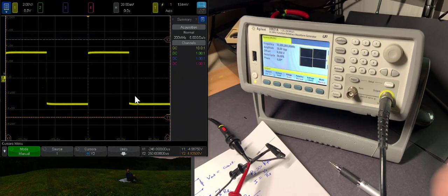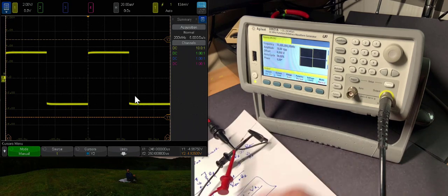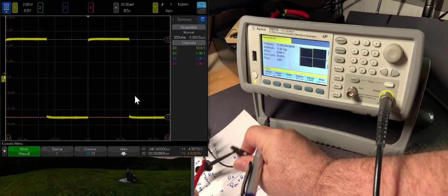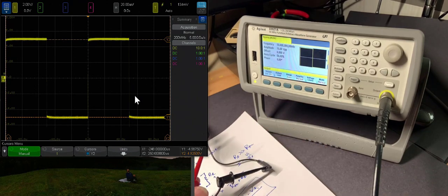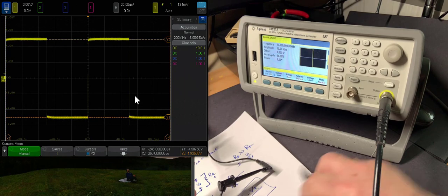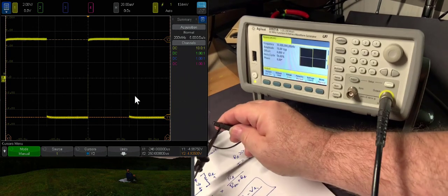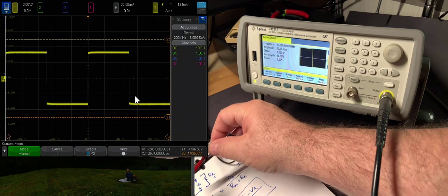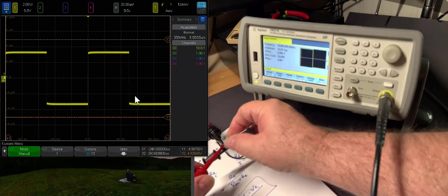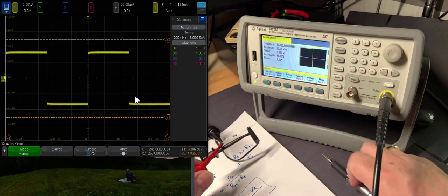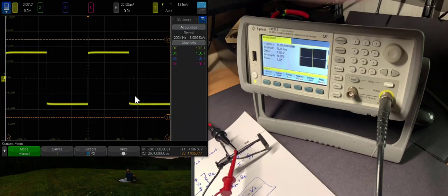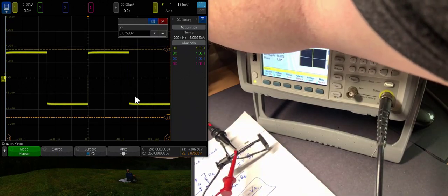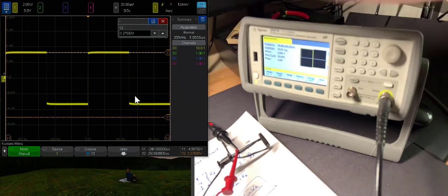And now let's see what that is. Because remember, the Thevenin voltage that we measured, we disconnect the resistive load. That Thevenin voltage, using the cursors here, is 4.925 volts. Now we add the 100 ohm resistor load, and I'm feeling it. I'm not sure I feel any warmth at all. We're in good shape with that. And now the loaded voltage is, again using our cursors, we'll move them down and read it off the front screen. There it is